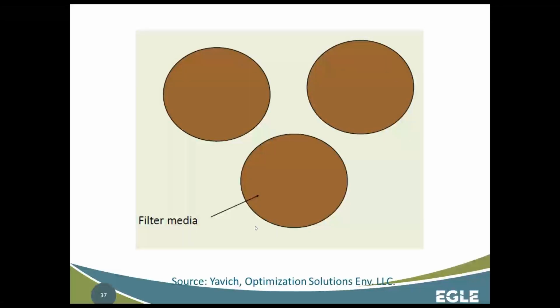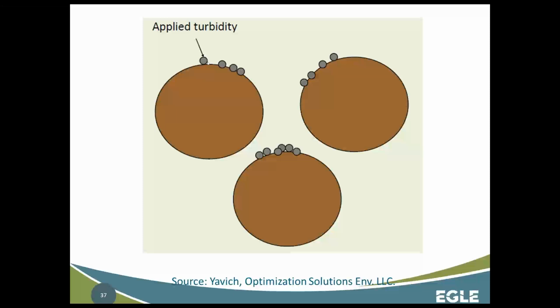We've been talking a little bit about particle attachment. We're going to take a little look at what that means. In this series, we're going to click through a few different images, which will depict the process of particle attachment and demonstrate that it's not straining. The particles that we're trying to remove are not going to get stuck in these spaces between the filter media. Instead, what happens is they come into contact with the filter media and they coat it and attach to the outside edge. As you can see, these could easily fit through between here.